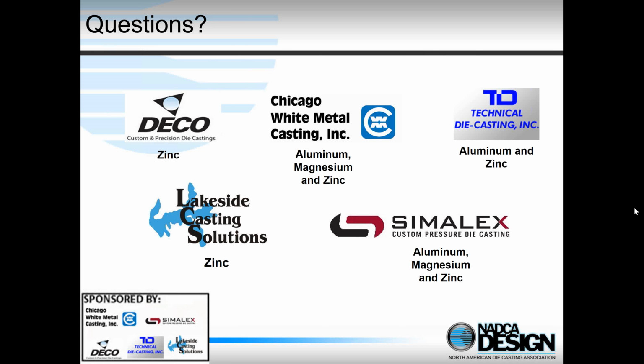But with a high integrity casting, a high vacuum die casting, a semi-solid casting, a squeeze casting, those tend to have much lower levels of entrapped gas, and so welding to those is much less of a problem. So if you want to weld to a die casting, you need to go with a high integrity type process. But again, why not make it all into a single die casting?